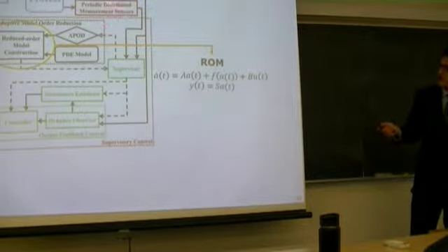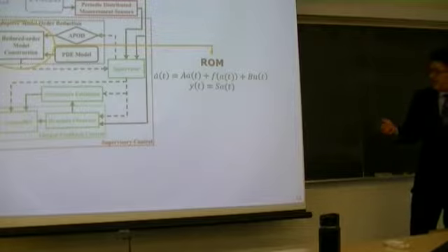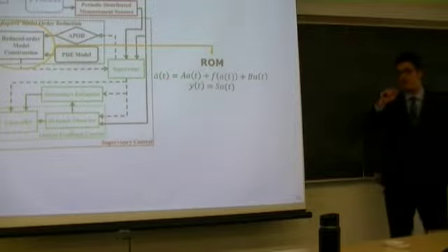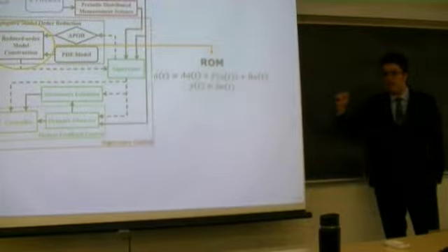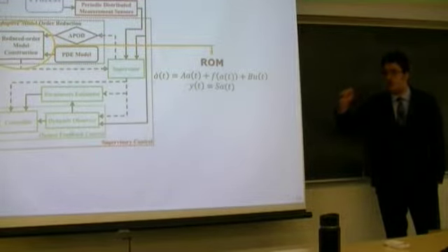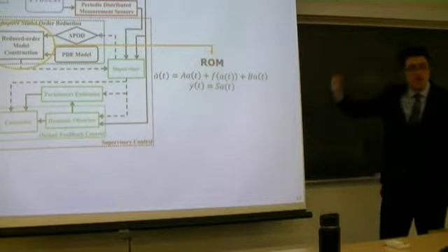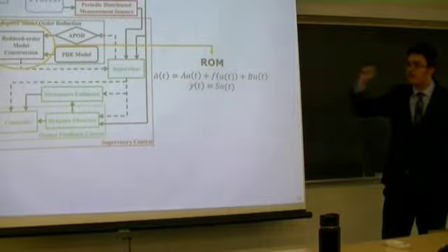Then we use those snapshots to build a reduced order model as a nonlinear ordinary differential equation with finite dimension. And we revise the reduced order model during the process evolution by monitoring the control Lyapunov function. When the control Lyapunov function is increasing, it means that we are not capturing the general dynamics of the process correctly. So we need more snapshots to revise our reduced order model